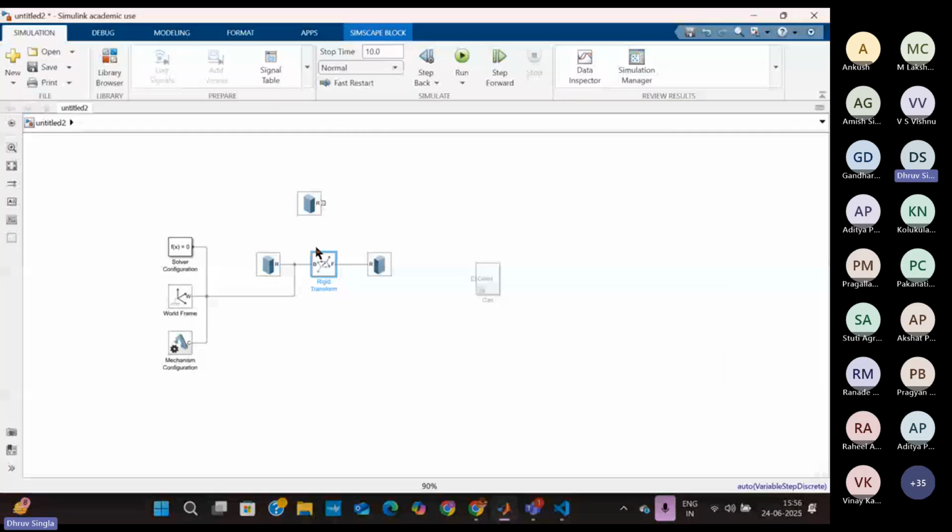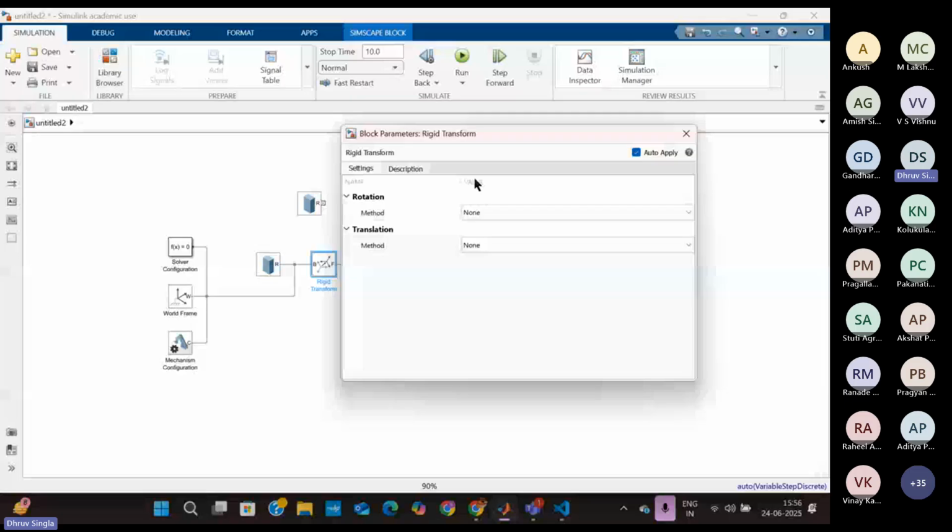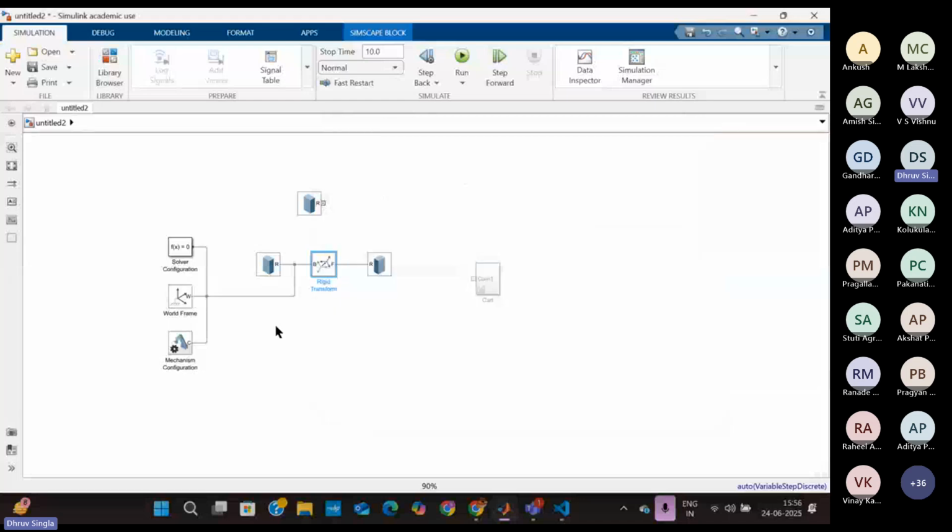And we'll do the same here. What we need to do for it is have a translation again in the standard axis, in the z-axis, of 10 centimeters, as we want the distance between the bottom two plates to be 10 centimeters. And now we have our two plates together.